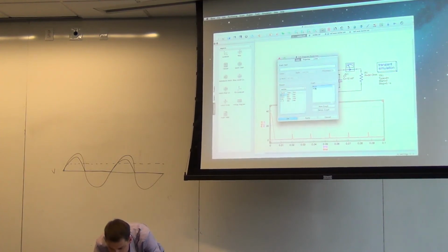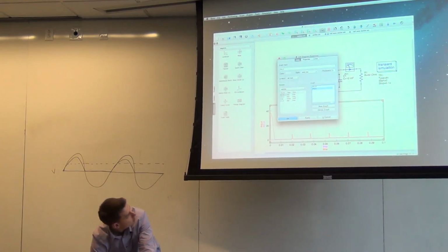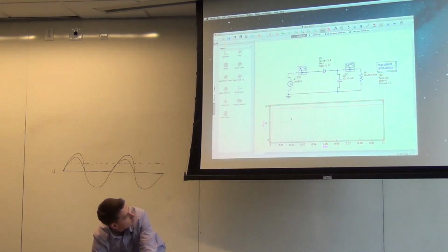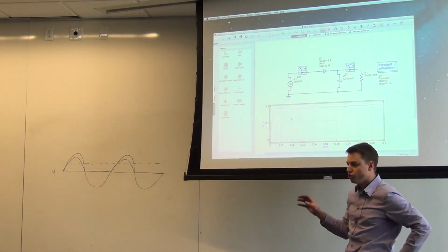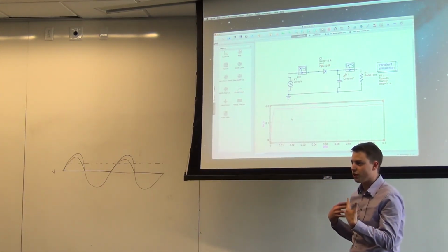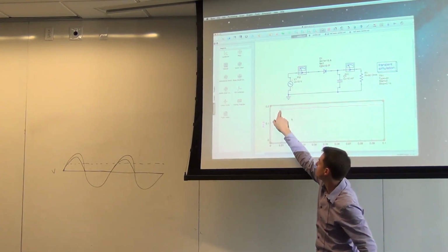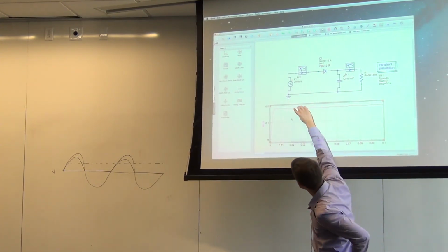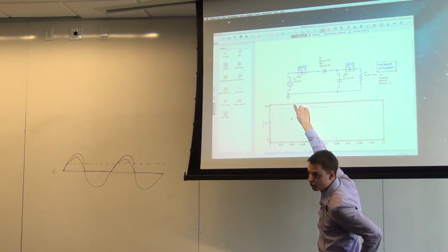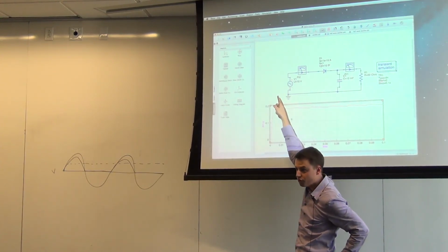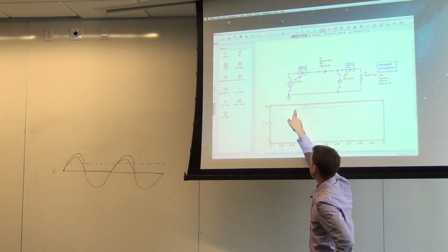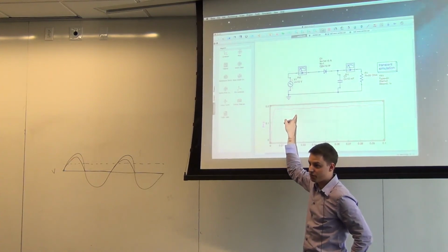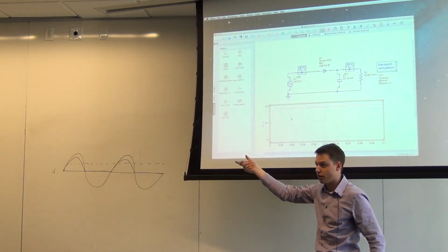So that's really cool. That's why the constant on the grid is that it has to be at 60 Hertz for voltage supply, but then the load will change the current draw, and thus change the actual power that you need. So the load will draw whatever current it needs as if it was coming from a DC source, right? It's just that the capacitor, so what's happening here is this is sort of the look of the current, right? So it's just this little blip right here that you're actually going to be drawing current from the voltage source, because that's when you actually need to recharge that capacitor. And then after that, in this range, the capacitor is just providing the voltage itself, right?